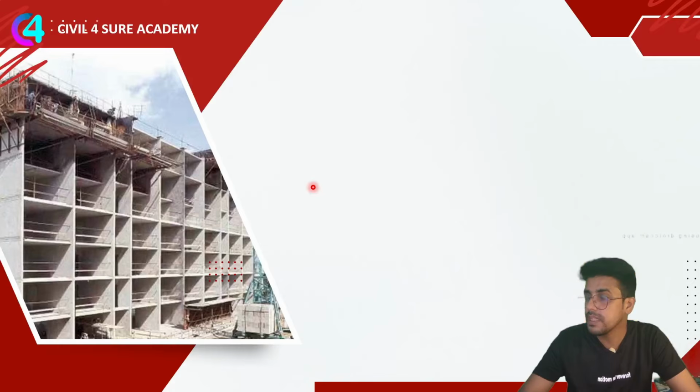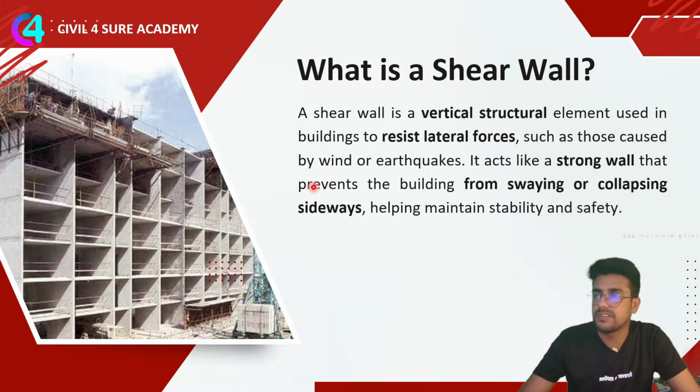Now, what actually are shear walls that we need to understand? What is a shear wall? It's a vertical structural element used in a building to resist lateral forces. It is not going to be like a common wall of brick or masonry. It is going to be of very rigid material, that is reinforced cement concrete, and it is going to be useful against wind and earthquake. It acts like a strong wall that prevents the building from swaying and collapsing sideways.